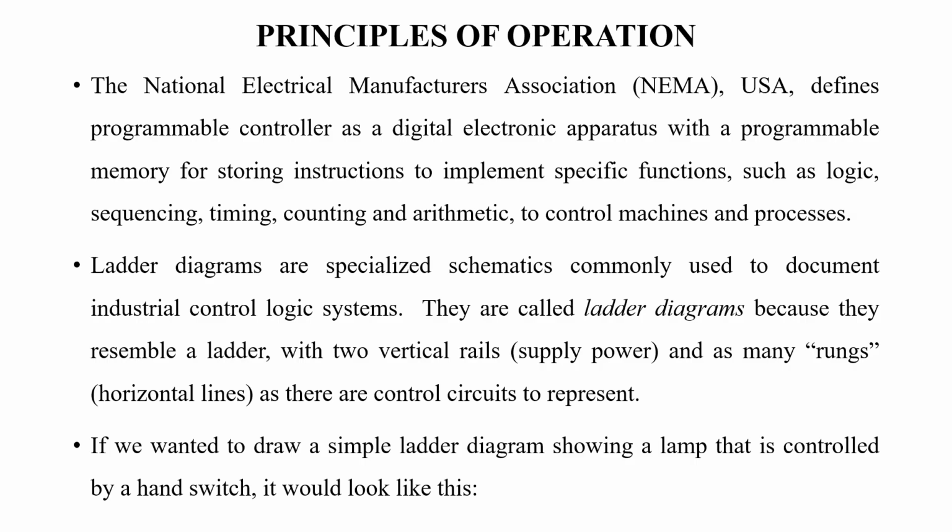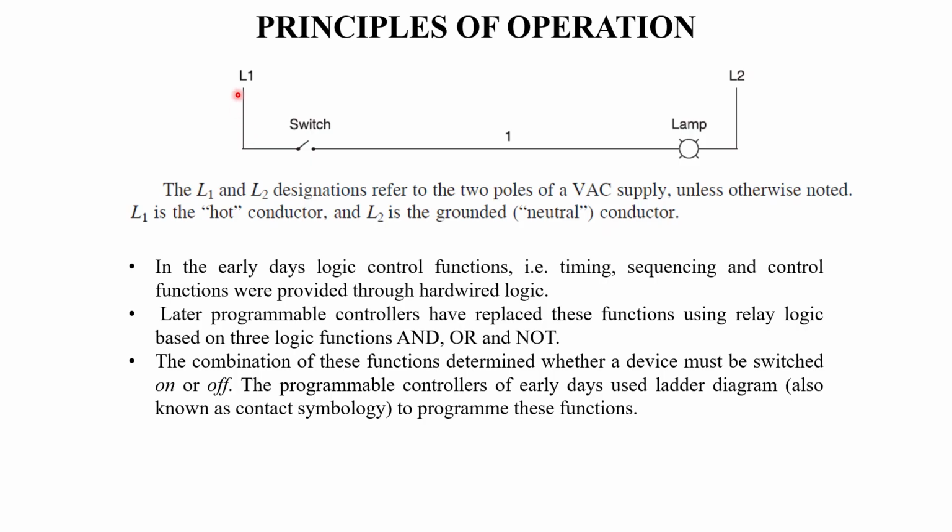If you take a program, you are going to represent the program with the help of a ladder. The ladder has vertical lines, and the control logic is implemented using the horizontal lines represented by the rungs. If you want to draw a simple ladder diagram showing a lamp that is controlled by a hand switch, the schematic will look like this.